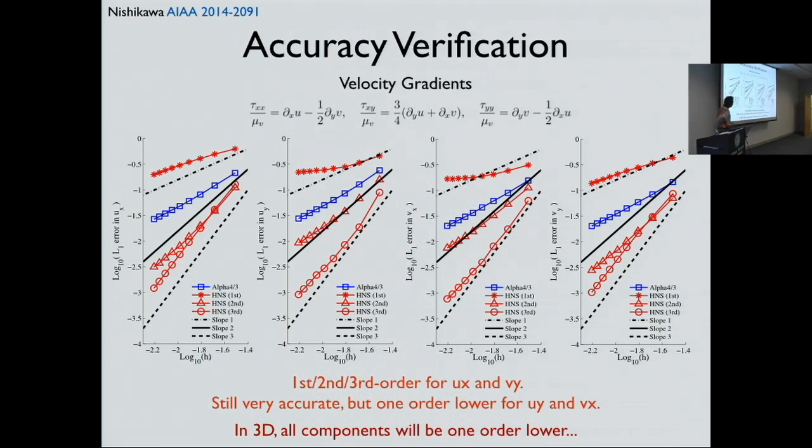So what I came up with to get high order accuracy was interesting. If you differentiate these 3 equations with respect to x and y, you end up with 6 equations, and second derivative of the velocity components, there are 6 components. So I can invert.